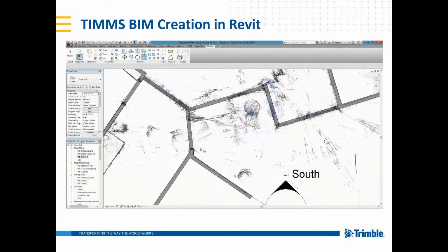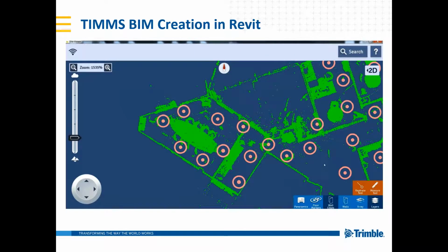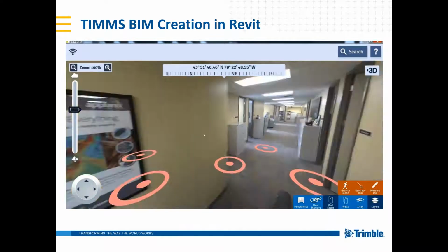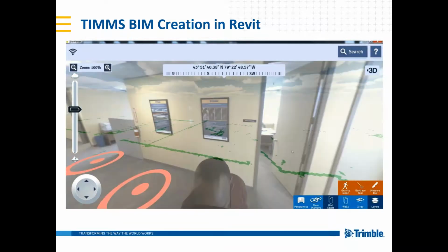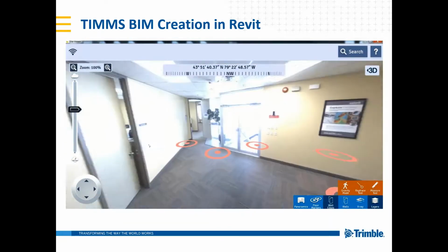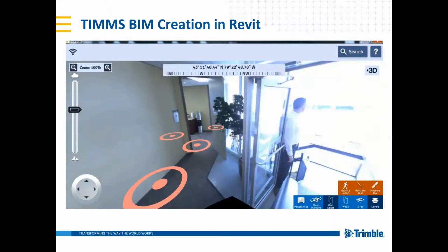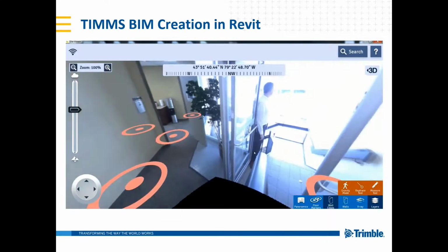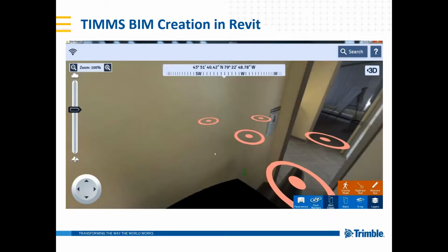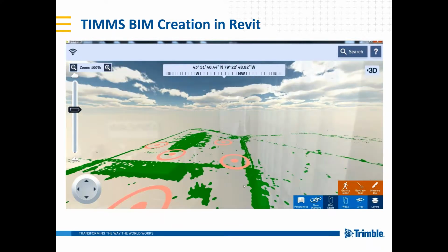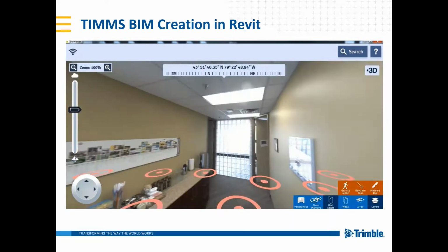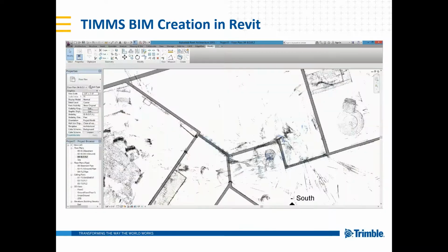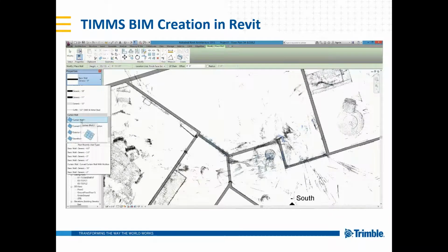Question on the board, will there be any effect if there is a water fountain or bodies of water in the building? No. You may get some reflections off the water from the scanner. Because we're moving, we're collecting data as fast as the scanner will collect it. But that means we can't take advantage of some of the automated filtering techniques that are built into scanners these days. Most of them require a heavy amount of filtering in real time or multiple passes of the same object. So you are going to see some noise due to reflections. As long as you're aware of that, then the operator tends to be pretty proficient simply ignoring it.